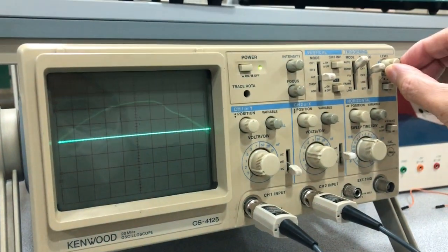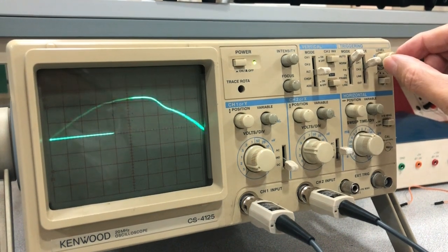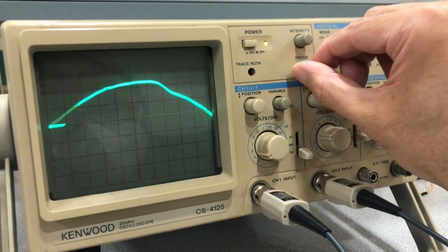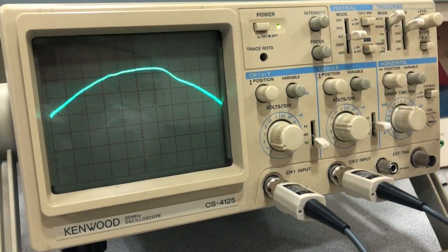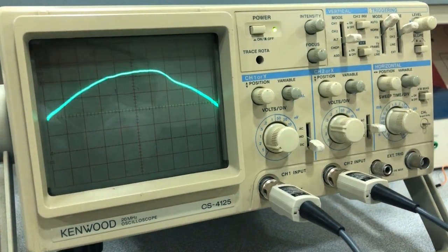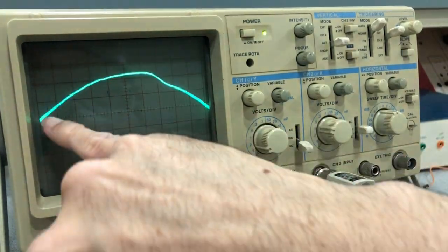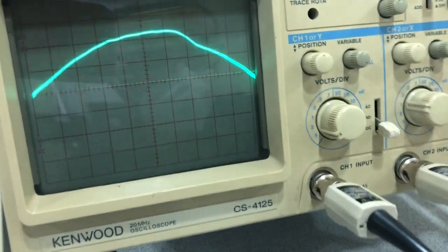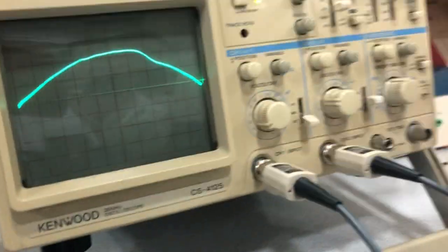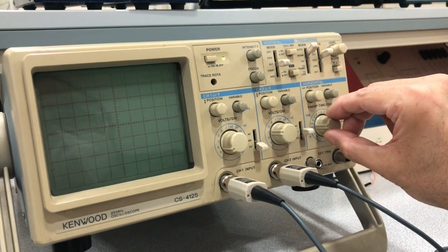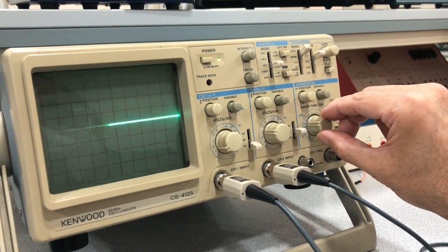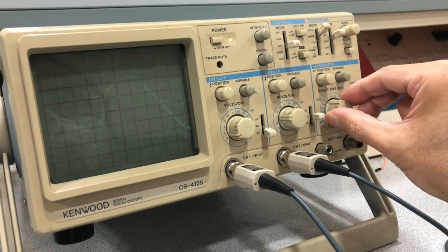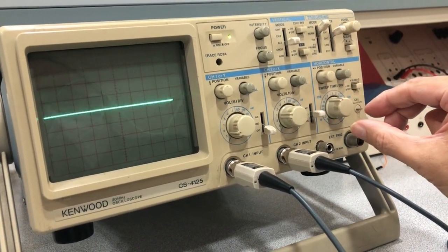I bring it back to the center, but I look at the screen and I need a better focus now. Okay, it is still focused, but this is the nature of the beast. This is a 50 hertz signal, and it's not going to be focused. These are old scopes. Notice here it's focused, but here it's not focused. And make sure magnification is not on. Because if magnification is on, notice how slow is the plotting of this signal, and it becomes very annoying. So you have to turn off the magnification, and you can go to a higher per division.